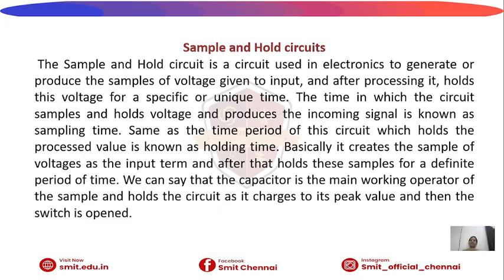Okay. So basically it creates a sample of voltage from the input. After that, first it samples, then it holds these samples for a definite period of time. So we can say that the capacitor is the main working element because it stores and holds that input signal. That's why we are using a capacitor here.